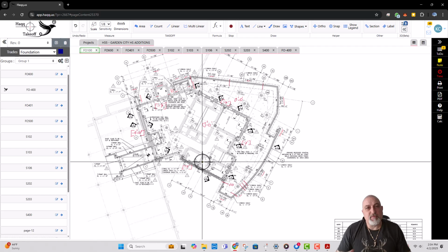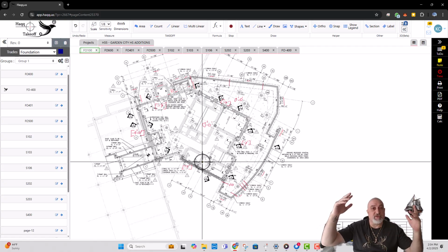You start the building from the footings. Actually, it starts with the excavation, but excavation is not my trade, so I have to start with the footings. Once I complete the footings, then I'm gonna go to the walls. But when you understand the footing elevations, walls will be easy. Walls usually go up to the top of slab elevation, which is 0, 0.